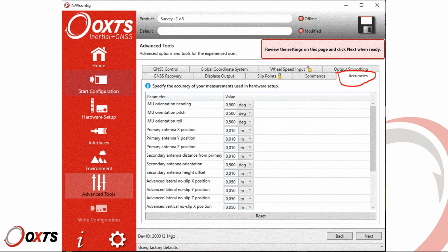So do not tighten too much. Just as much as you think it's correct, and possibly slightly more than that. So if you are super sure that you consider your distance measured, for example, to be accurate within 1 centimeter, perhaps set the tolerance to 2 centimeters.